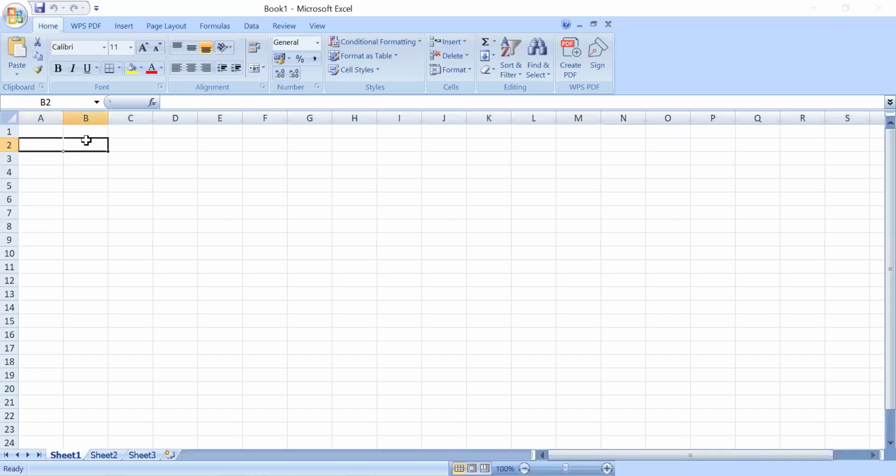Here I'll write VC is equal to 1 volt. I'm keeping this as constant. Here I'll write VB versus IB, VB in one column and IB in another column. Okay, so here I will take the readings.